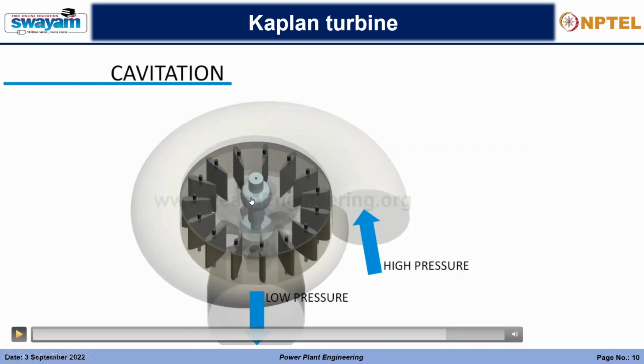Actually, what I meant about the swirl of flow was that the guide vanes are arranged in such a manner that they have more component of the velocity in the tangential direction, so it will rotate or revolve around this axis, right? So it will not try to go inside from the shroud, it won't try to go through this in the axial direction.